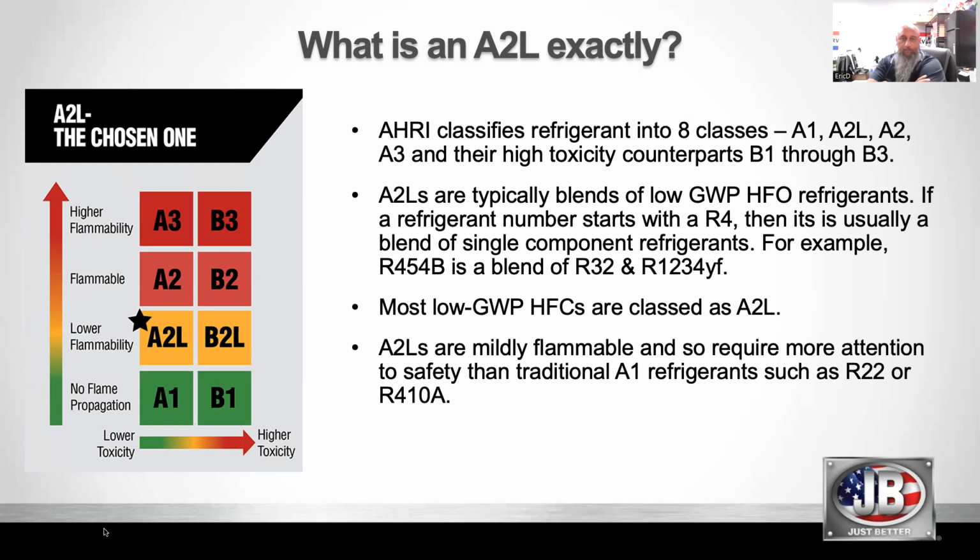And I suspect that a lot of the manufacturers out there have decided to go R454B for various reasons, whether it's the fact that it's got similar pressures to 410A and it's going to be an easier transition over. But I also think they've looked at what the GWP of R32 is, and it's very close to the 700 threshold that is mandated. And I suspect they're going to tighten it up as the years go by, and there's going to be pressure on R32 to be transitioned out, and potentially R454B as well, as we get more and more issues with global warming. This industry used to be an industry that didn't change much, but I think we're going to see a lot of changes a lot faster over the coming years.